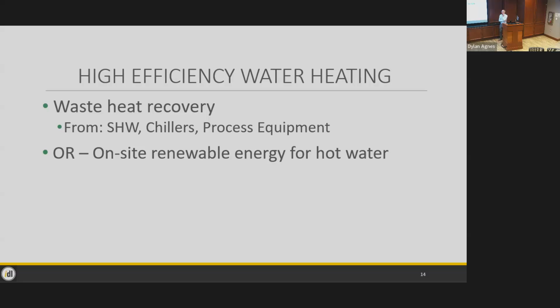So, I still love the idea of solar water heating and some of those DIY things that you can do with soda cans and things like that. But economically, solar panel photovoltaics have just come down in cost so much that from a cost perspective, that tends to be the cheaper way to go rather than using solar thermal. But if your client really wants to do it, it's super popular amongst the architecture students upstairs in their thesis projects. You can get a credit for it and meet the 406 checklist. That'd be one way to do it.